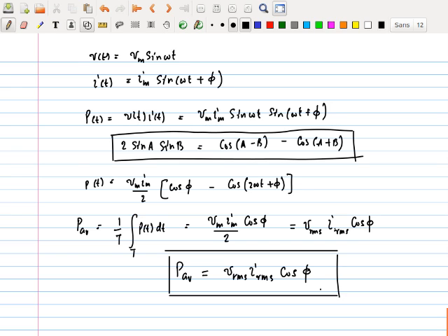Put all the things which have inductive loads. Look at a machine, what do you have? It's a coil. Coil is what? An inductor. A blender, what do you have? A coil. The moment you put a coil, it's not a resistive load. You say, don't bring irons, because they're purely resistive. Don't bring any of them. Motors have bigger coils. Bring them to my house, because the more inductive you make it, the angle increases, and if it's a pure inductor, how much is the angle? 90 degrees. Then what happens? No electricity.